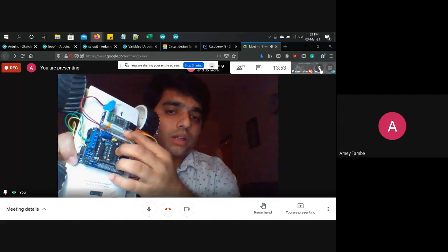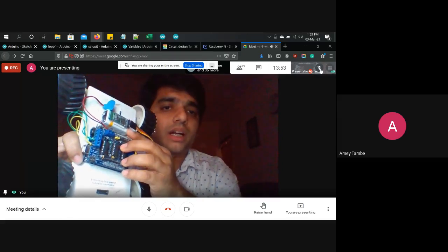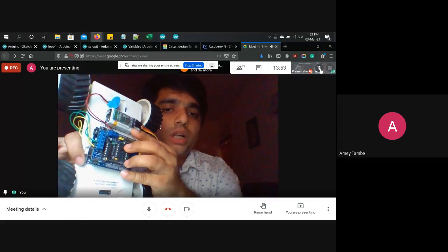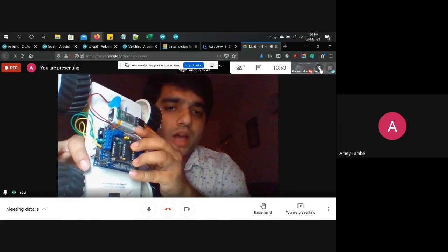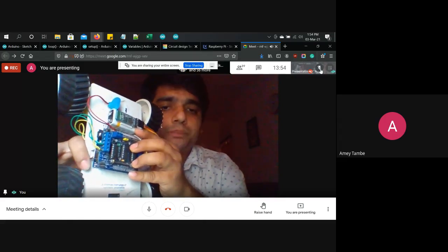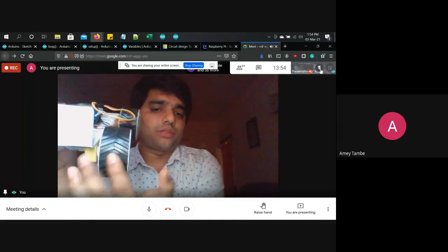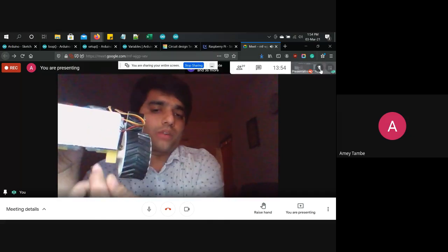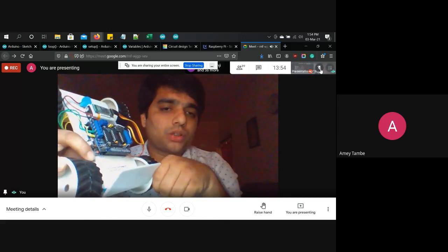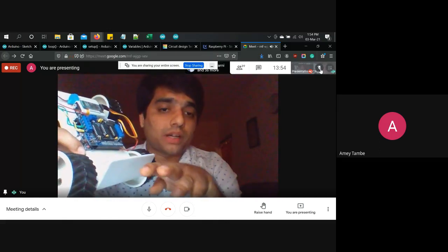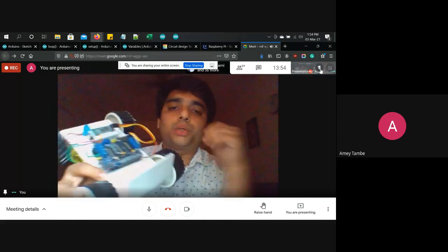I'm having a 9-volt alkaline battery, as alkaline has a good power capacity, meaning the current which is flowing is good. If you use a normal 9-volt battery, it is also fine, but my experience with that was very bad in the previous version of this rover, where I had smaller wheels. The wheel gauge is much broader here. I was using a normal 9-volt battery, so I connected 4 batteries to it, but it was not getting sufficient power, and then we need to control all these motors.